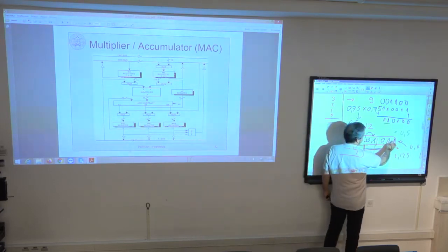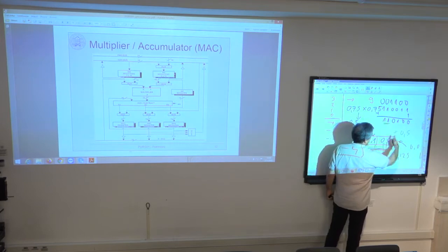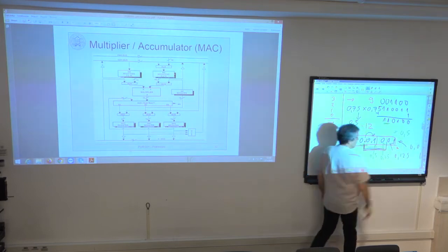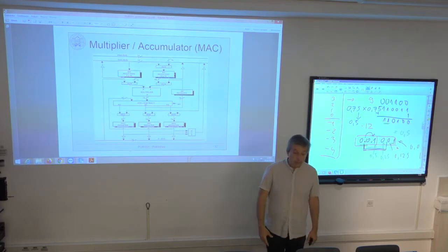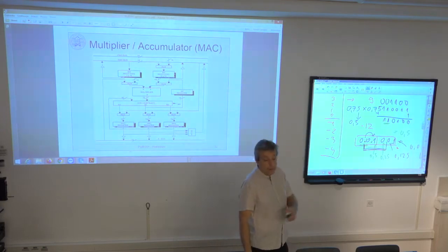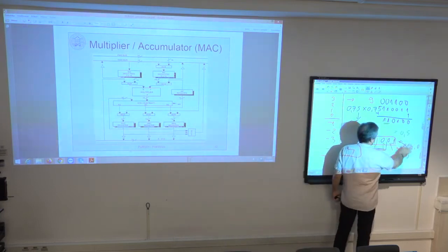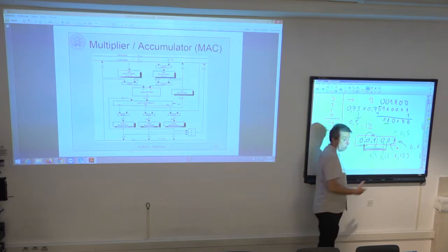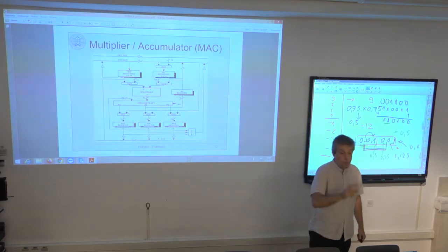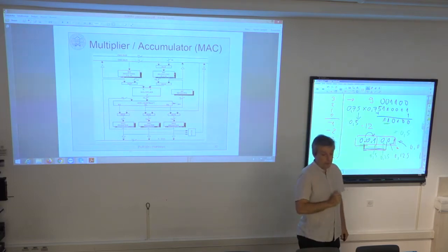So the rounding would be by asking ourselves whether this remainder is greater or less than half. If it is less than half, I can discard it, because in this case the error would be negative, but at most 1/2 of the least significant bit.